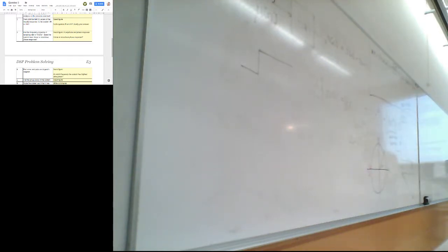Okay. In case our phase response is linear, meaning it is the same as a constant times omega, it basically means that part is sine of omega times (t plus k), meaning that if you have a linear phase response, then the time delay through the system is constant.